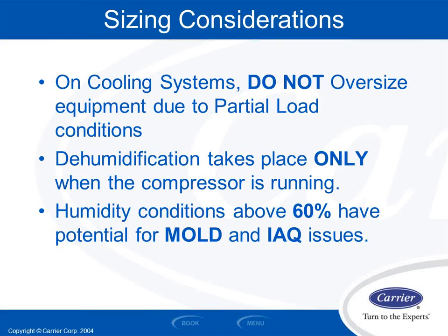The other thing I could do is slow down airflow. Sometimes, if we have a thermostat that has a humidity sensor in it, we'll have what we call a dehum terminal on that stat, and that wires to the dehum terminal on the HVAC equipment. Dehum basically means that my thermostat is happy from a temperature standpoint, but it's a little bit high on the target for whatever humidity I set it for, say 60% in our example. So I'll ask for dehumidification of the HVAC equipment.